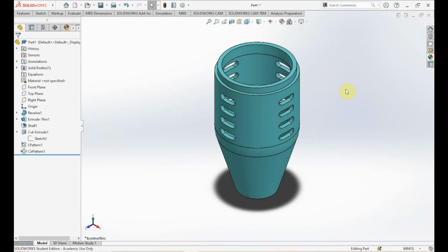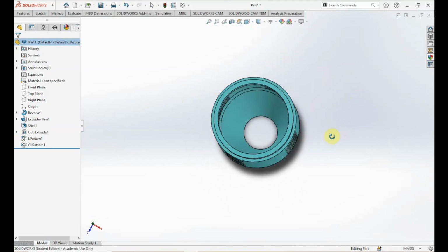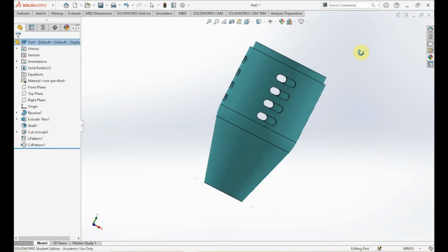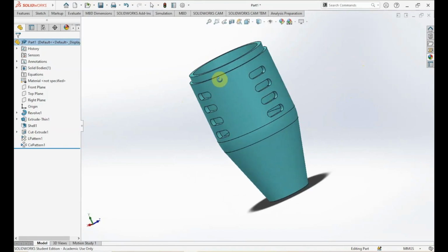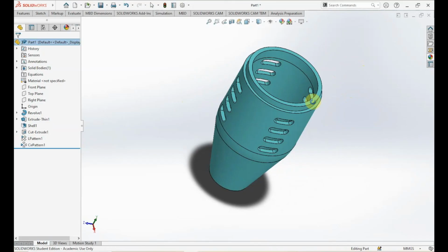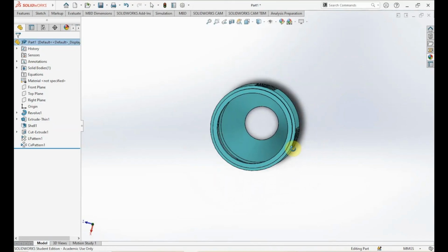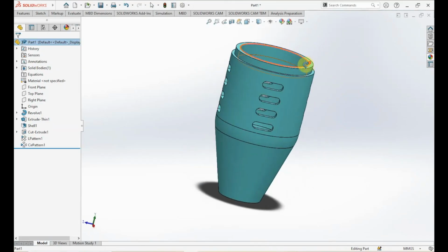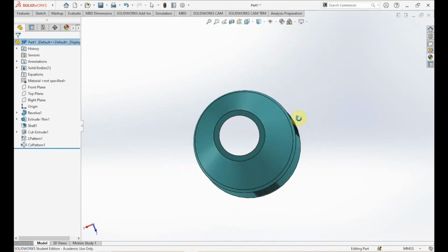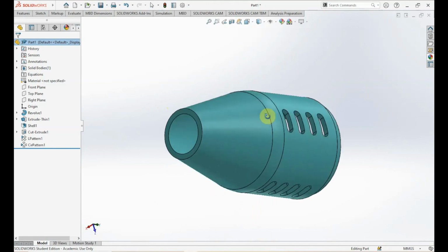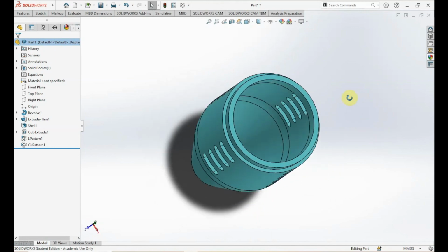We have finished designing and sketching and extruding this piece. It is a simple microphone shell. We hollowed out everything out. We created 4 instances around the revolved piece, creating oblong cuts. We learned how to use circular pattern. We learned how to use linear pattern and some other features that you guys probably knew how to use. But this is basically the whole piece.